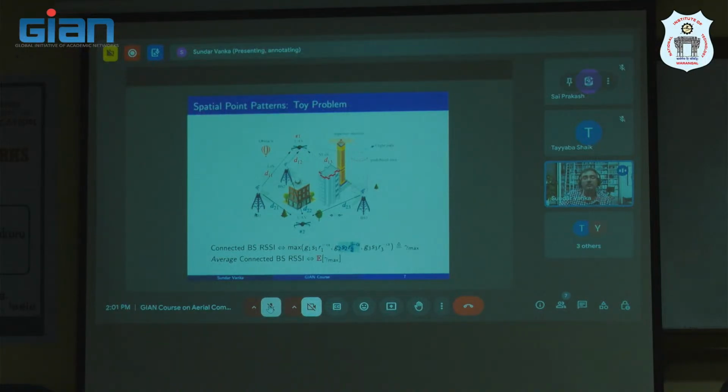I will need to find power connections that can be used to serve these base stations, and also hook them up with a backhaul. So all these considerations mean that once I install these base stations, I will not move them. I found these base stations, the lease site. I installed it on a building or on the ground somewhere, and I left it.